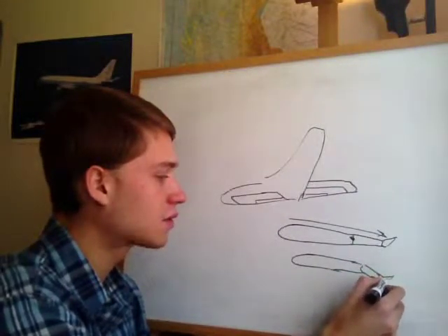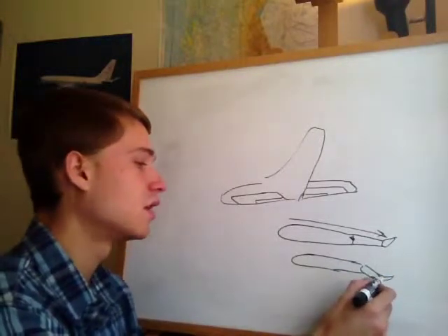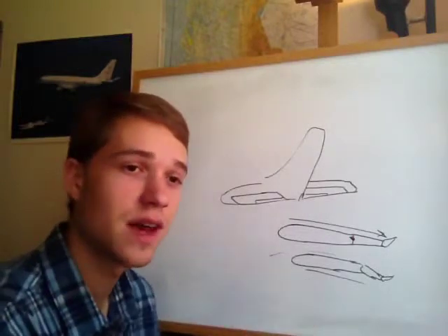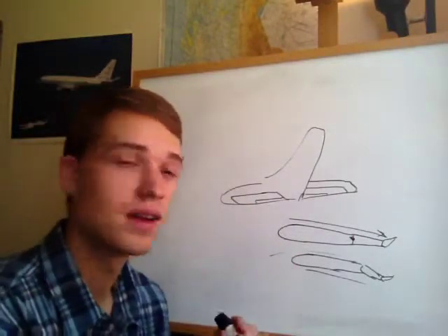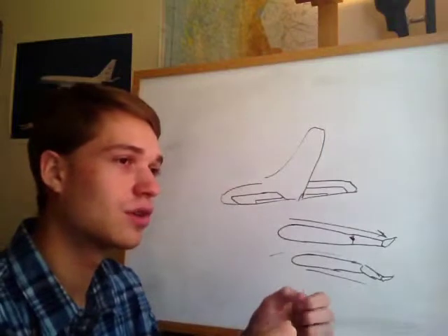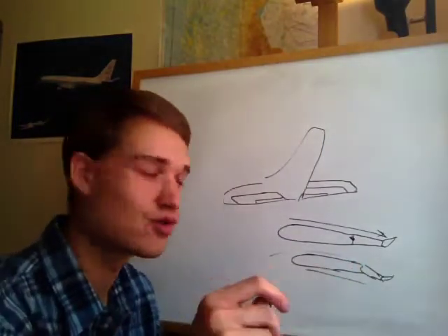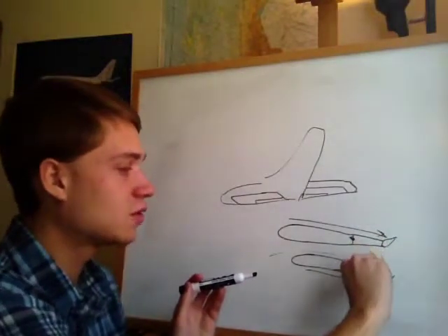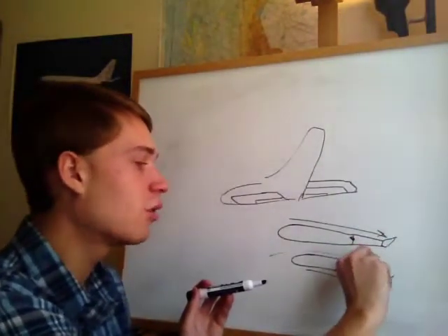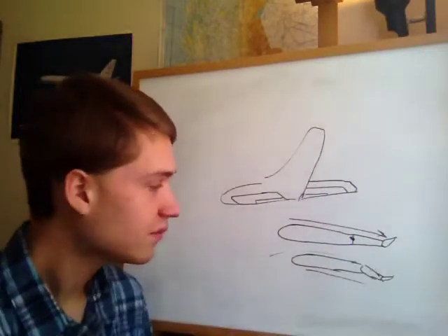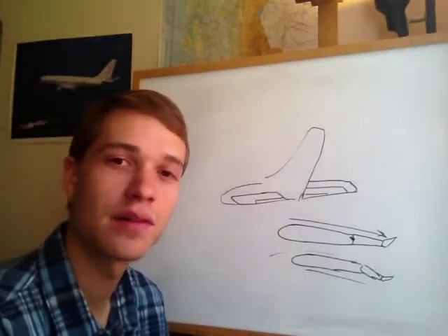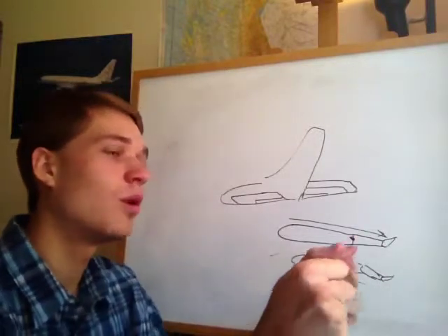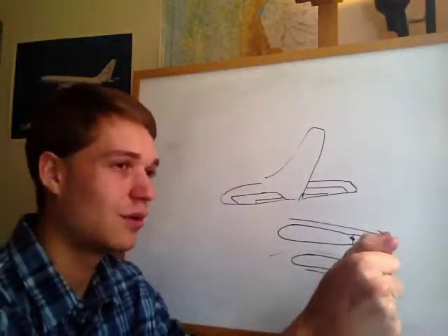And so now it's going to hold itself in this position in the airstream all by itself without you having to do that. That's how the pilot can hold the elevator position without actually holding the controls. He'll set the trim wheel, it'll exert this aerodynamic force, and then it'll reorient itself in the airstream, and then you can fly the airplane hands off. Now you can enjoy your 3-hour flight without having to hold pressure on the controls for the whole flight.